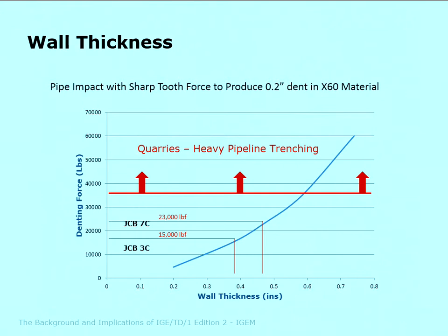The design factor, I use this slide because this is the original research slide that was presented to the committee which was developing the standard. And what they did was they looked at essentially where you move from having a failure mode of a leak to a failure mode of a rupture. And the concern here was corrosion defect.